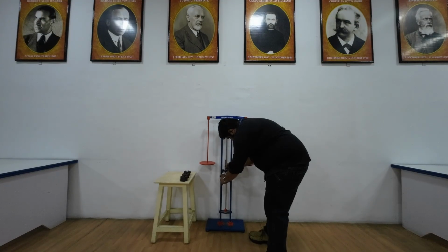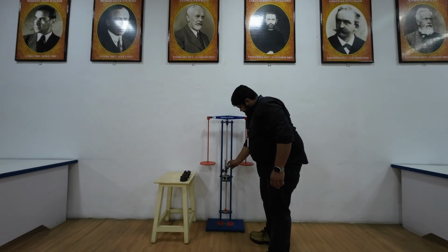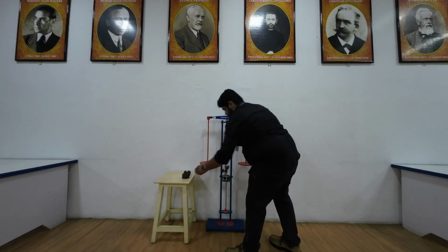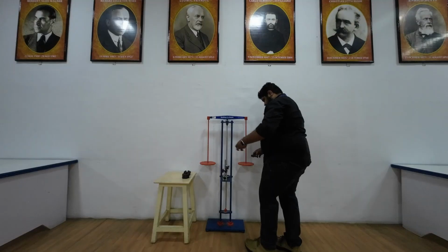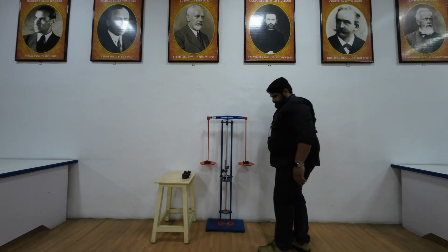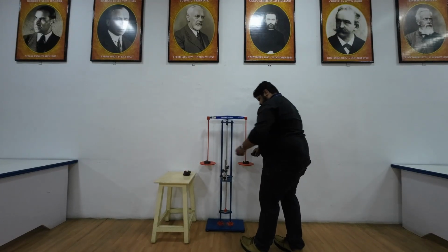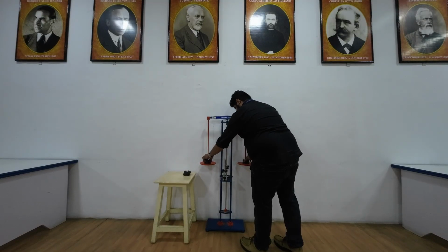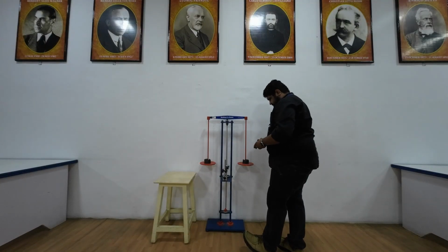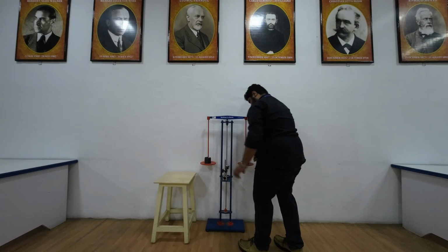The dial gauge is placed in the direction where it bends. Next we need to set zero. Then we can apply loads and start measuring the deflection. We can go for 3 sets of loads or 5 sets of loads, and we will be able to find the deflections against the applied load.